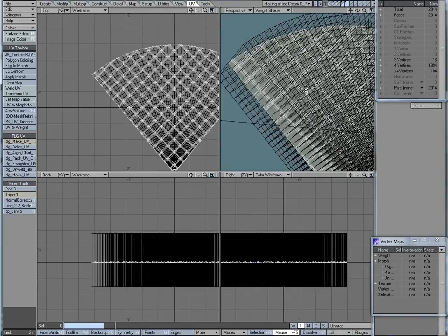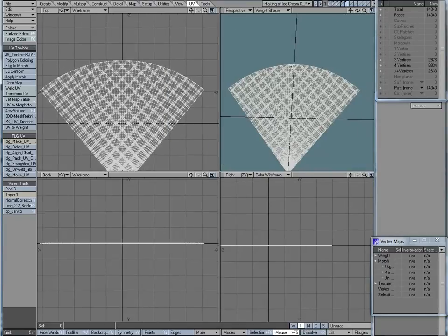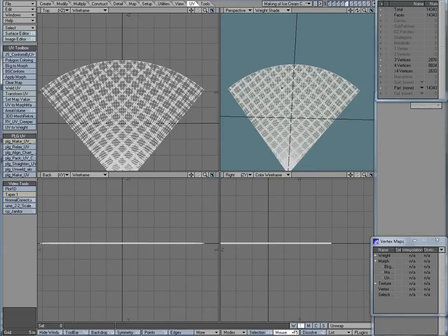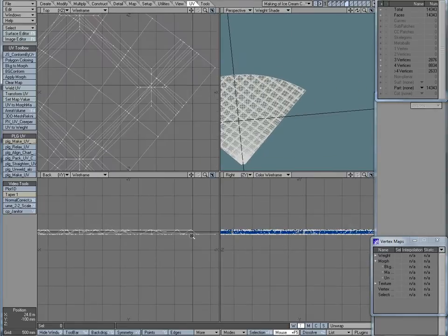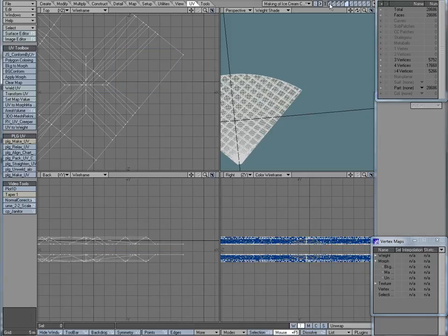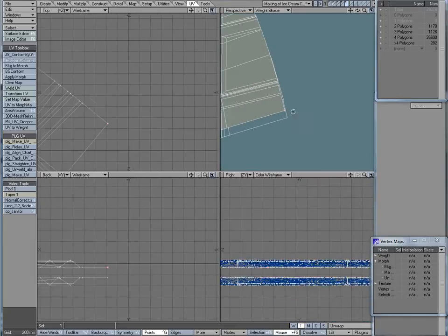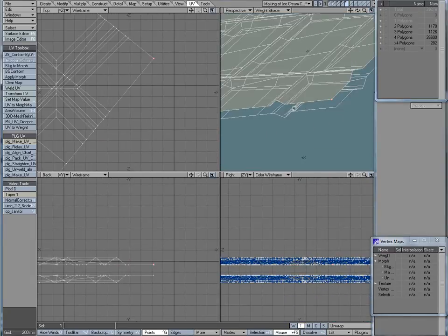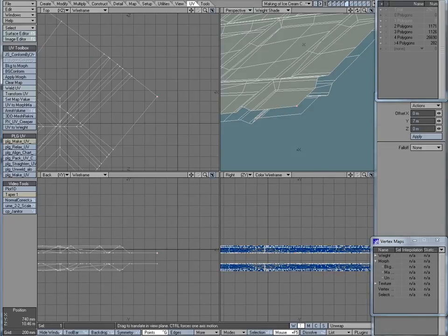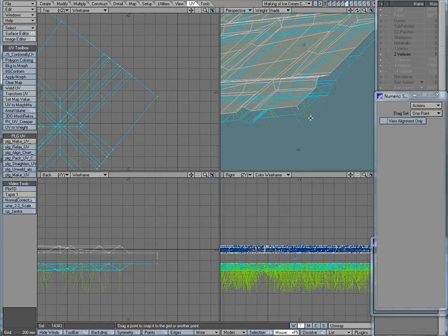So now after this done, I can give thickness to the cookie. So I got both my outline cut and my grid cut. And so now I'm going to give some thickness. For that I'm going to basically just mirror it. Okay, and I'm going to focus on this point. So I want 100 millimeters thickness, so I'm going to extend this point, push it down 100 millimeters numerically. And I'm going to use a snapback tool to just snap that whole side to that one point.